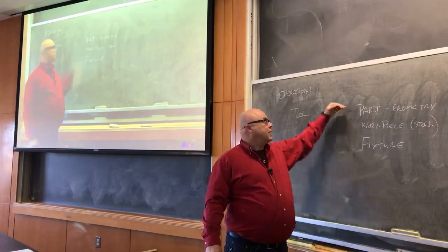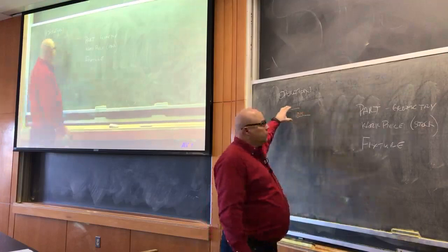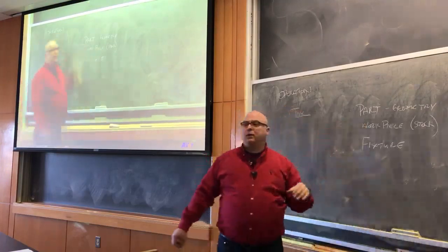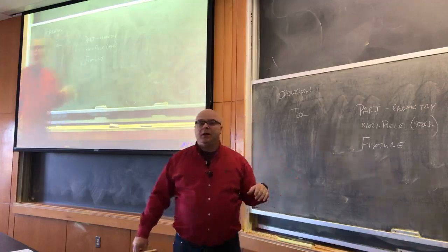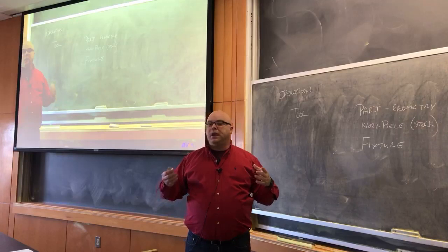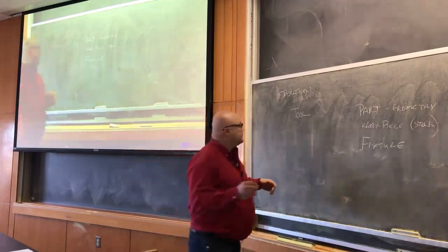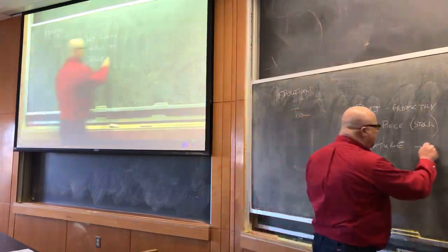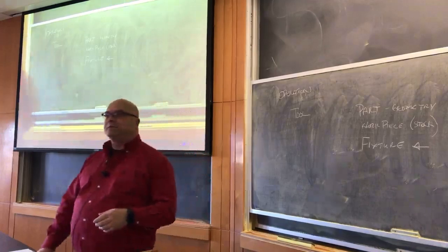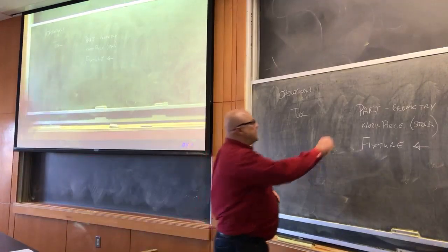You should concentrate on figuring out what it is you want to make. It's very difficult to ensure that you chose the right tool if you don't know anything about the workpiece. And so the tool we can pick before we pick the fixturing, but once we get to the point where we have to decide the tool path, one of the critical things that we have to do is make sure that the tool path does not have the tool run into the fixturing. So I think we have to have that fixturing defined here. So we have to know all this stuff.